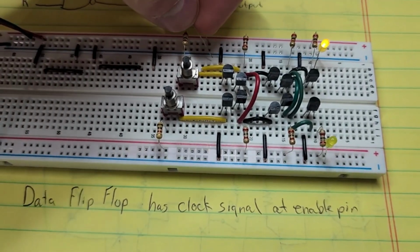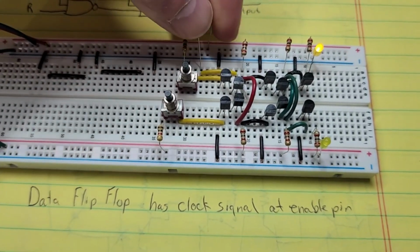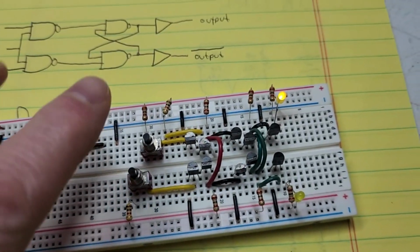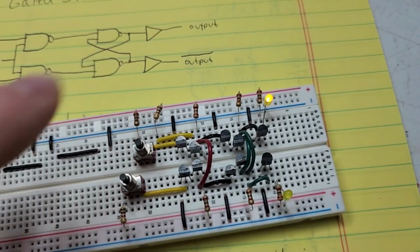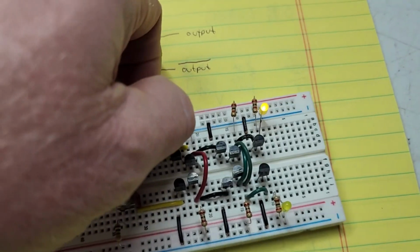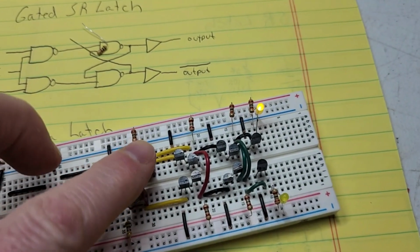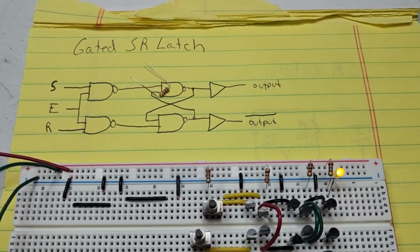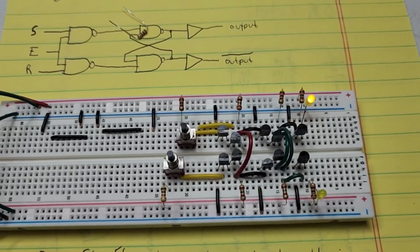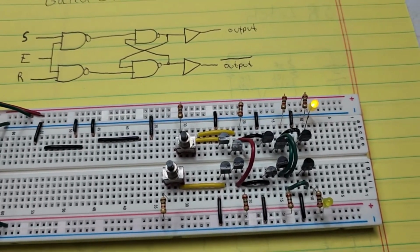Let's see if I can do it. Put the enable resistor back in. And now I can reset it, set it, reset it, set it. I can get my bits set, remove my enable, and nothing works again. See? So I can permanently set that bit. It's kind of cool, right? So that's the gated SR latch. So we're going to do one more latch type in this video of latches.